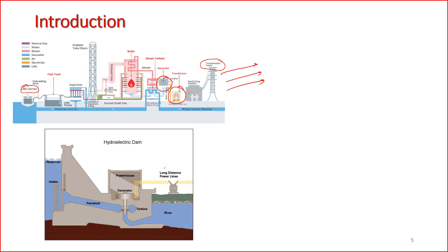And similarly there is hydroelectricity, we can see hydro generation. Here the water is injected through the penstock to the turbine, right? Here the generator is vertically placed. Generally hydro generators are vertically placed, and this is your turbine blade. When the water is injected, the generator rotates and produces electricity, right? We'll see how it produces electricity. In fact, this is the objective of this course. We'll see how synchronous generators produce three-phase power and it is transmitted.